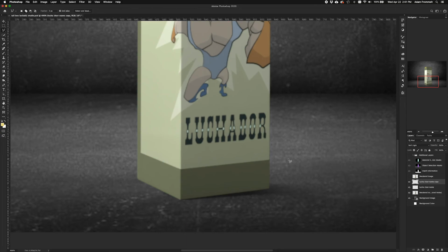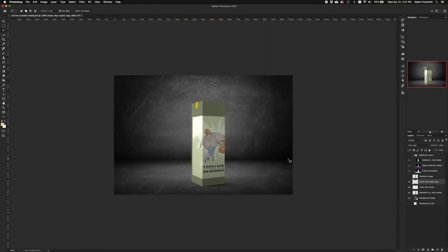Okay, this is close. I would spend a little more time adjusting that in so that it looked totally correct with the perspective. I'm slightly off on this angle, but that's a quick post adjustment. And then the other thing also, if you needed to, let's say that I felt this was a little dark around the edges. I could add a brightness contrast adjustment to it, lighten this up ever so slightly, and while I was in here, I'd probably bump the contrast to about 10, okay? So now I could resave this as my Photoshop file, and then flatten all my layers and kick out a regular image that I could place into any layout software that I need to be working with.